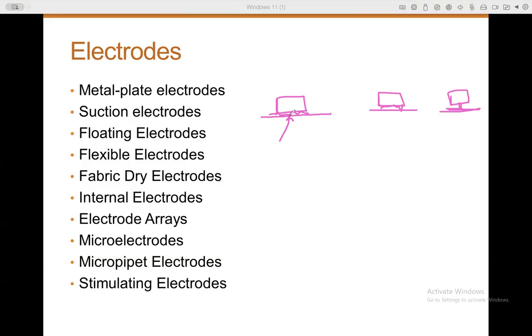So once you connect this, you're good, you're solid. But if you have another electrode here, and this gel goes all the way, this is what we call the webbing effect. Basically, instead of getting two different signals, now you've short-circuited this. This doesn't quite happen in gel electrodes. So with gel electrodes, if you want to take a recording for 2-3 hours, the gel is pretty good. You stick the electrode on and for 2-3 hours, this gives solid recordings.